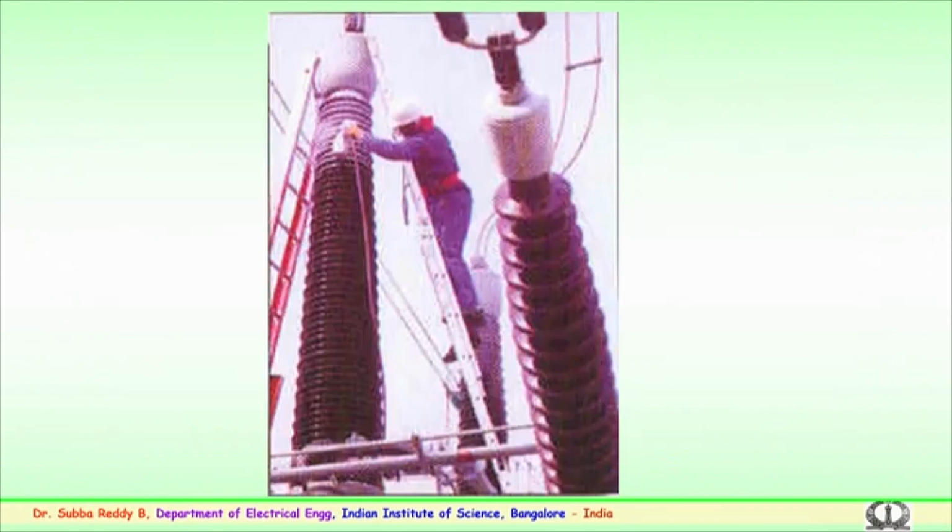One example here shows the coating of insulators on a bushing in a substation. A room temperature vulcanized coating is being applied on the surface of the sheds of the porcelain high voltage bushing. In a transmission or distribution system, this could be a CT or a PT bushing in the substation.